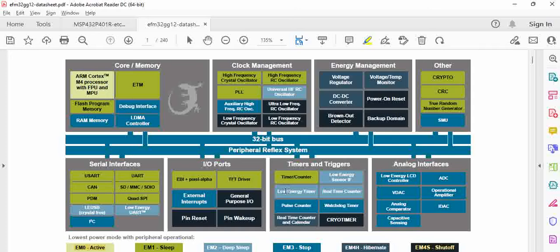considering the quiescent currents on your board. So ultimately, even if the microcontroller supports it, the board design that you do should support the low power operation. If the microcontroller doesn't draw, it doesn't mean your circuitry around it doesn't draw. So you have to design your circuit properly, and you have to select your devices such that you have very low quiescent currents, and also you plan your power management on your board such that you get the lowest power possible out of your board.